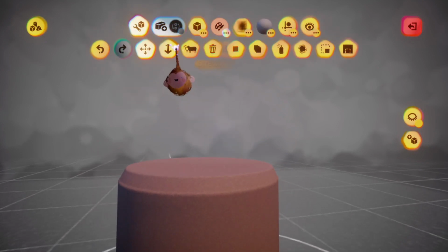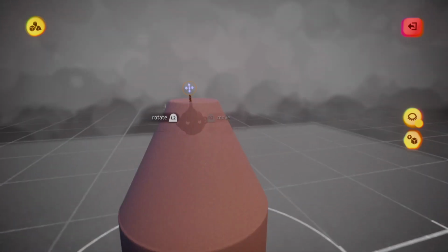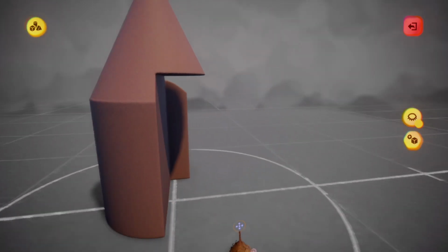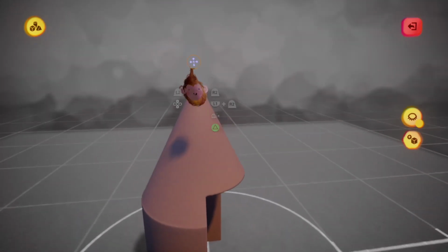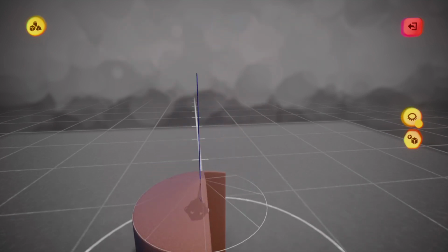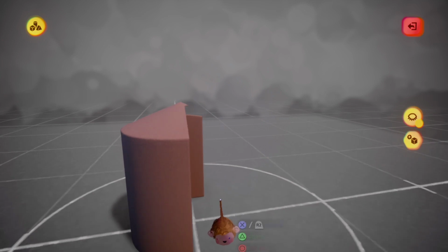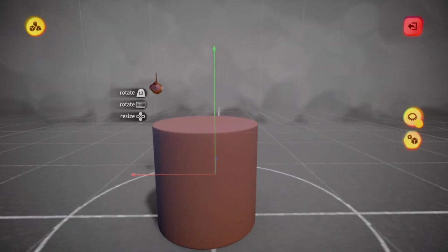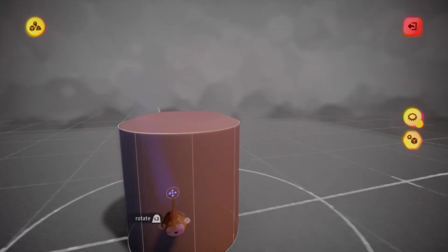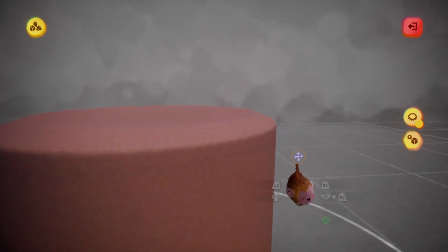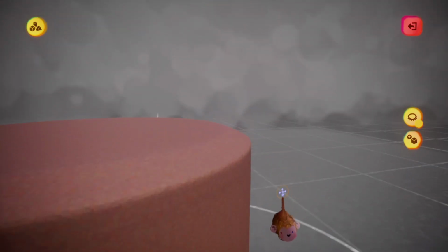And if I want the angle here to be more steep or slanted, I can use the stretch tool. So I might move this crop to the side so that I have room to scale the cone. So I can make the cone more flat. And then I can move the crop back to position. And now I'll get a flatter chamfer.